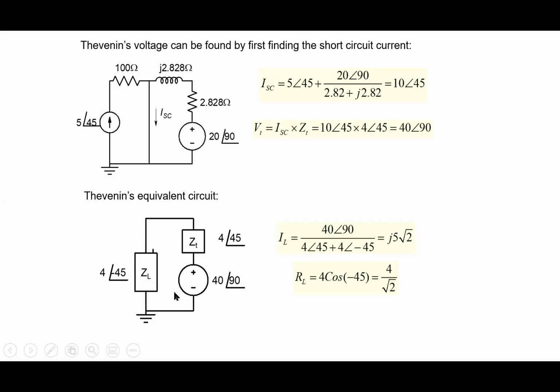That's the IL. So when you have a simple circuit like this, our strategy is to find the magnitude of the current that is flowing here and look at the resistive part of the impedance. Basically power dissipated would be I square RL. Remember, there's no power dissipated in the reactive part here, either the inductance or the capacitance. So that's why we are finding IL, and we'll focus on the magnitude part of this.